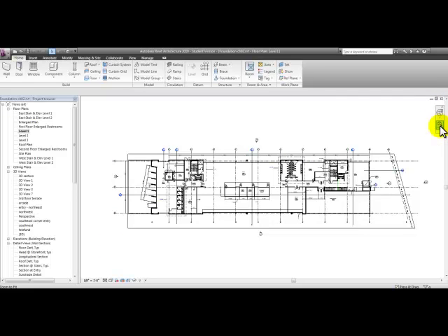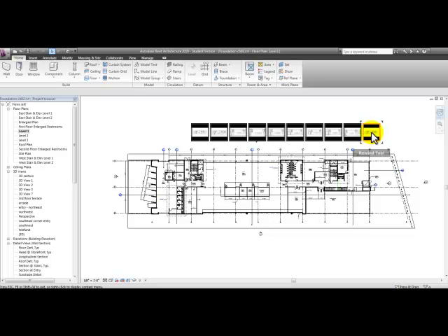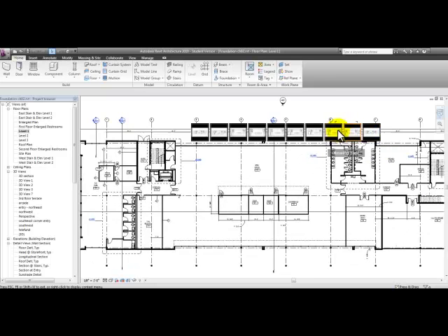access quickly the zoom commands here. Zoom region is similar to zoom window, and zoom fit to zoom extents. The 2D steering wheel gives you controls for zoom and pan, and with rewind you can display several previous views and select the one you need to view.